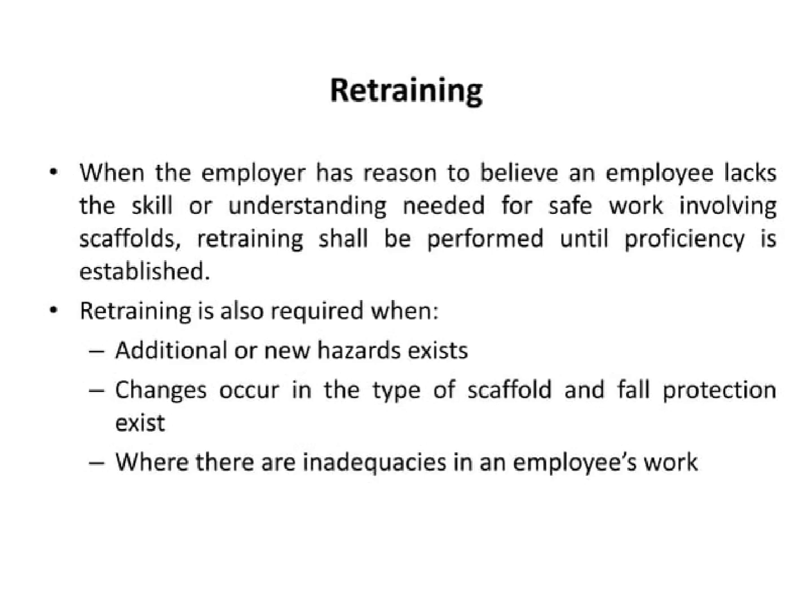In addition, retraining ought to take place when new or additional hazards present themselves, variations occur in the type of scaffold, or new fall protection systems come into effect. Moreover, when inadequacies are seen in an employee's work, another retraining session should be conducted.